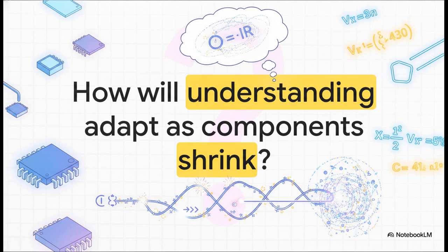Through this experiment today, we've seen just how crucial it is to verify these principles, watching out for pesky errors like test lead resistance, port connections, and taking precautions to maintain constant temperatures. Because ultimately, deeply understanding this fundamental relationship between voltage, current, and resistance is exactly what allows us to build the modern world safely.